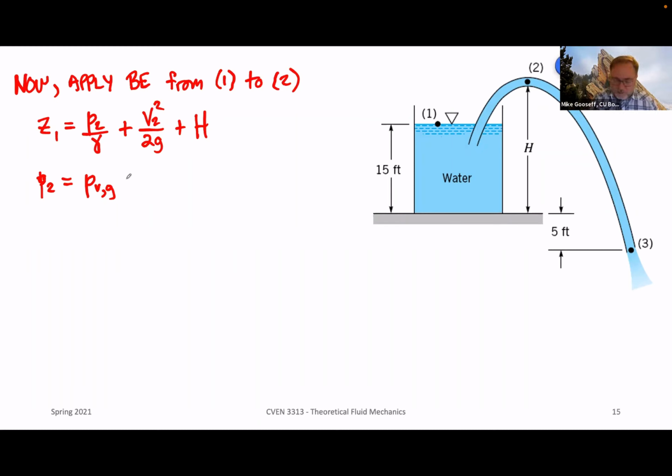So this is going to be equal to, we were given 0.2566 PSI for the vapor pressure minus 14.7 PSI, which is our atmospheric pressure. So what that means then is that P2, and it should be a really low value, it should be less than atmospheric, is a negative 14.4 PSI. Okay, and yes, we will convert that to pounds per square foot here in a moment.